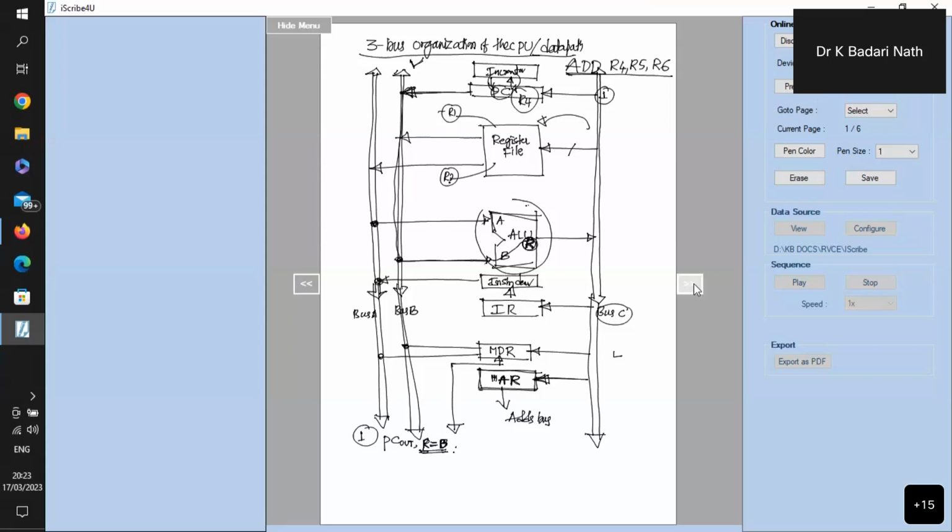Now I got this one. Then as usual, MAR in we have to give, so that it is written into the memory address register, and it also generates this address onto the memory address bus. Now in parallel, I can initiate a read signal, and I can also increment the PC, program counter. All this is possible because there is a separate incrementer available. So the moment I say increment PC, what will happen in this clock cycle? The program counter's value is taken to the MAR, and is also copied to the incrementer to perform +4. So all this can happen in a single clock cycle.